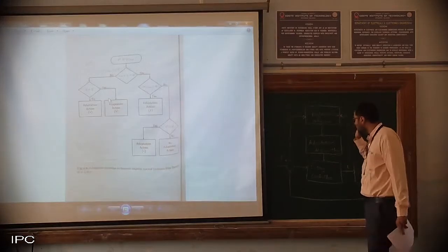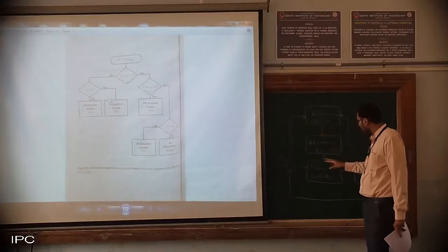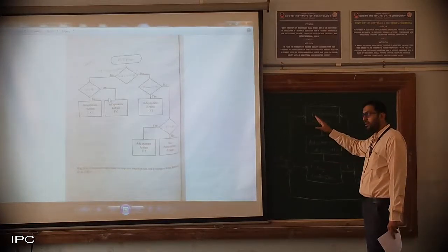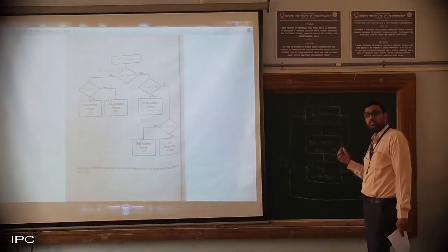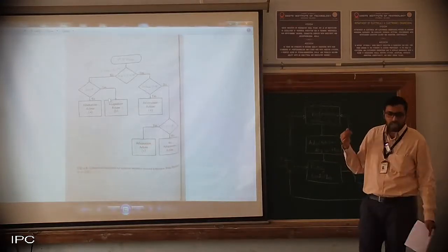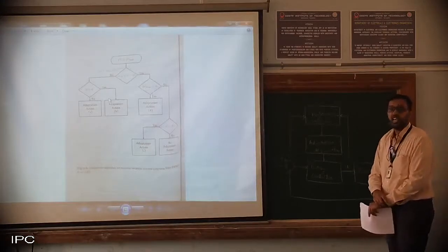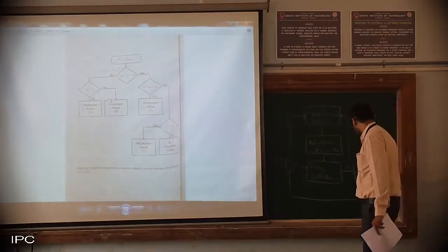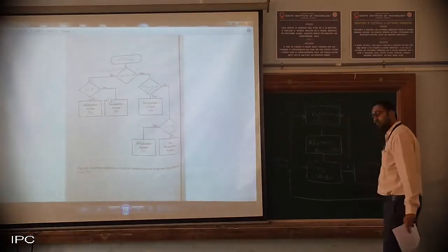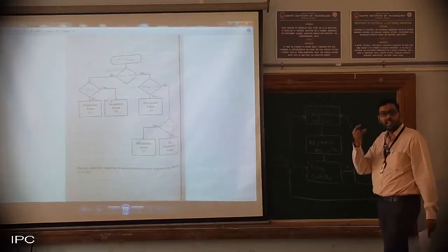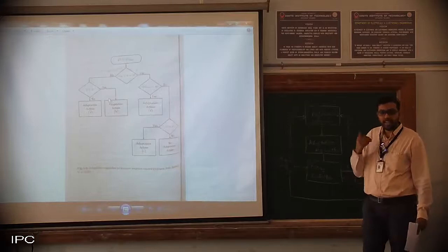So we are basically tuning the values of Kp and Kd such that our error becomes minimum and thus our performance is high. As we have seen, the inputs are error and change in the error. The output is the required change in the control output. So how much change has to be done? For example, the requirement was 1500, but our output was 1480 RPM. So there was an error of 20. So what does our PD type of controller have to do?